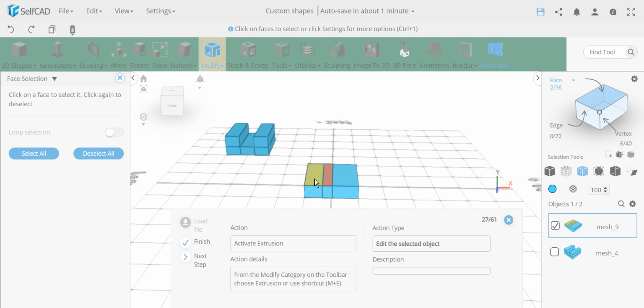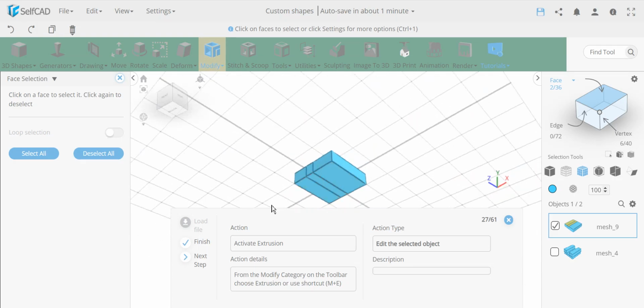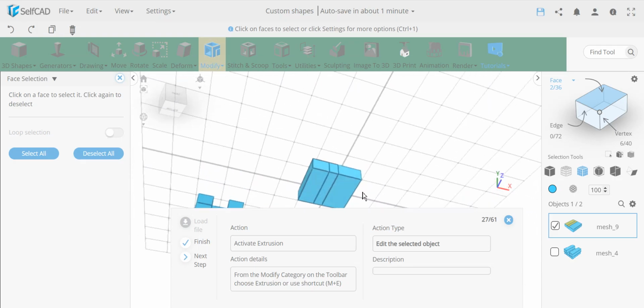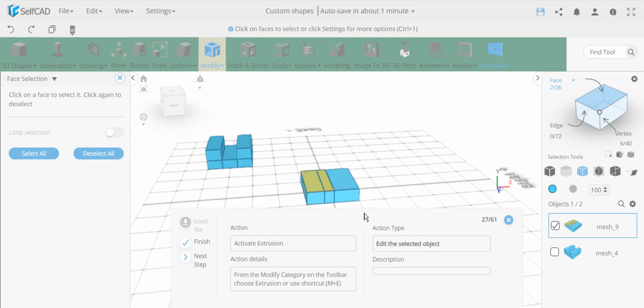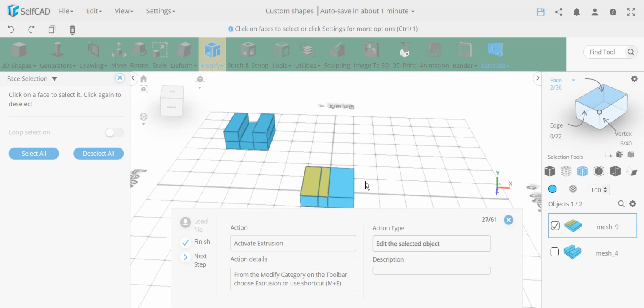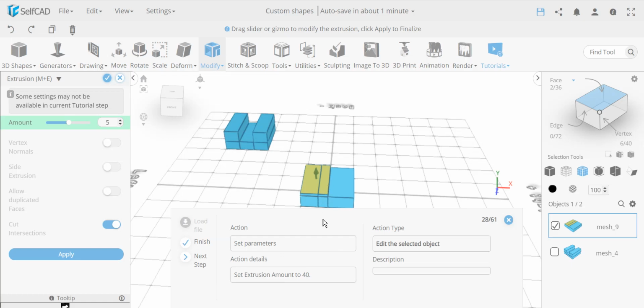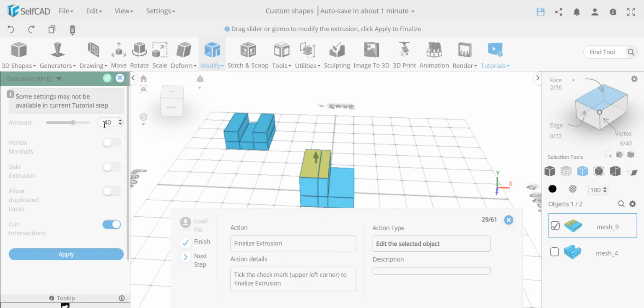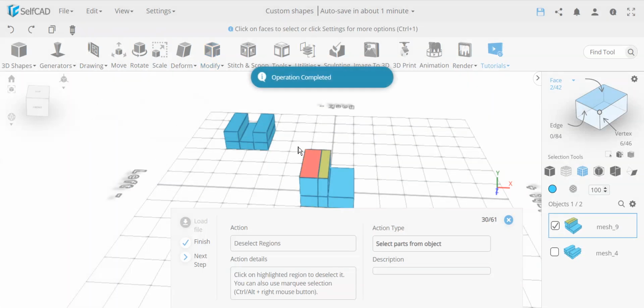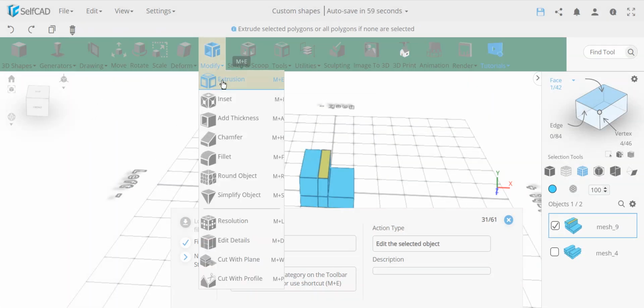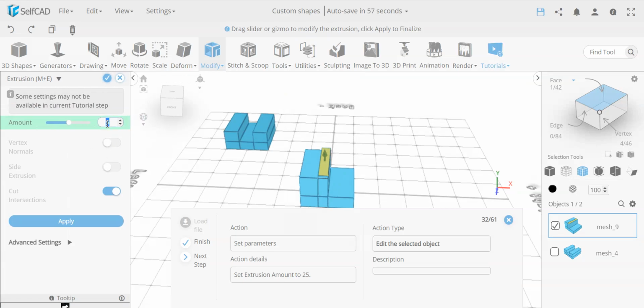Now we selected these 2, we turned it off, because otherwise if you would have it on, it would select the entire loop, which in this case would already be, if you see, we will already have 8 faces, so loop can work even on hundreds of faces. But nevertheless, that's basically the idea over here. And what it's going to do now here is extruding this to 40 and reconfirming it. And now it deselects only 1 section and then it extrudes it again to 25.